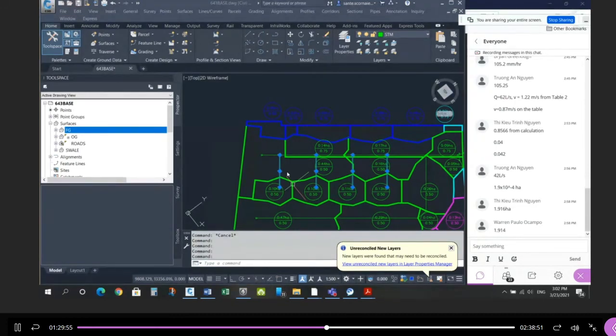So without designing each individual one, by each area, what's the flow based on 0.1, what's the flow based on 0.12, 0.11, and so on, they just say, look, if we determine the maximum area for a generic size of a 0.5% slope on a 250 pipe, as long as we check the areas are less than 0.19, we know that size is going to work everywhere.